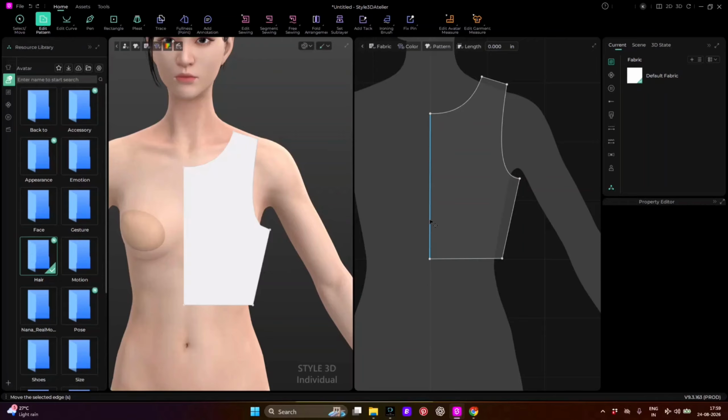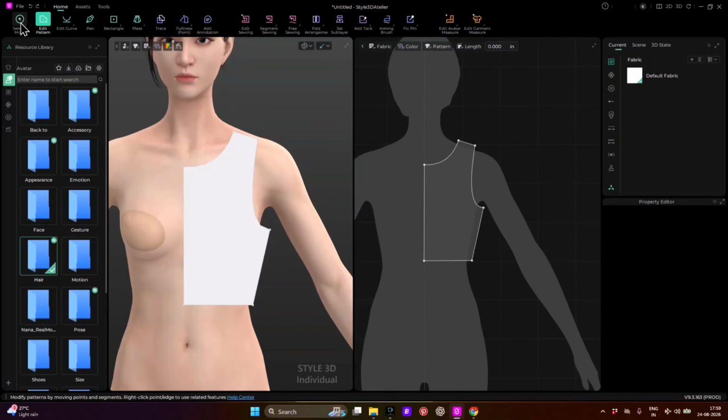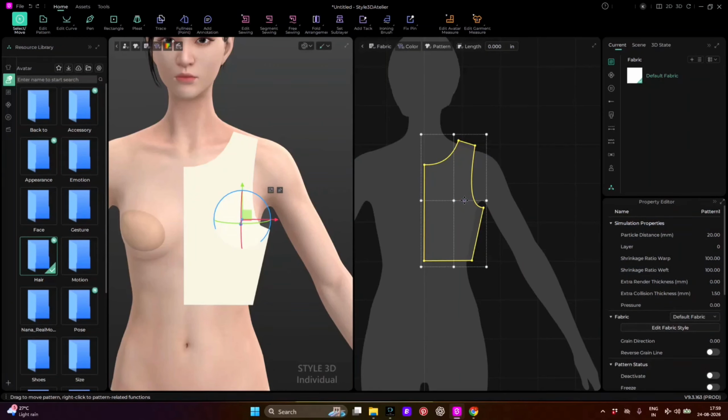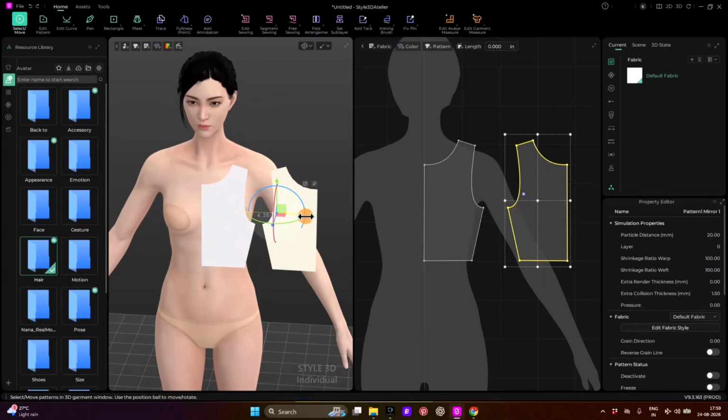Now, in real life, you will place a fabric and turn it into on fold side, and then you will draft the front bodice, right? So, before you do that, go to your select and move tool. The shortcut is Q and select it. Hit Control C and Control R to replicate the back pattern. Now we have two things to work with.